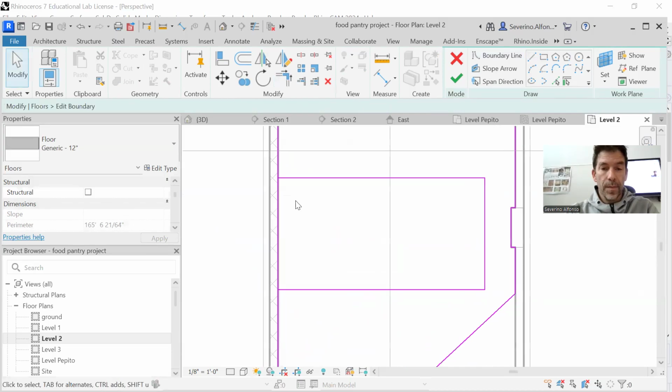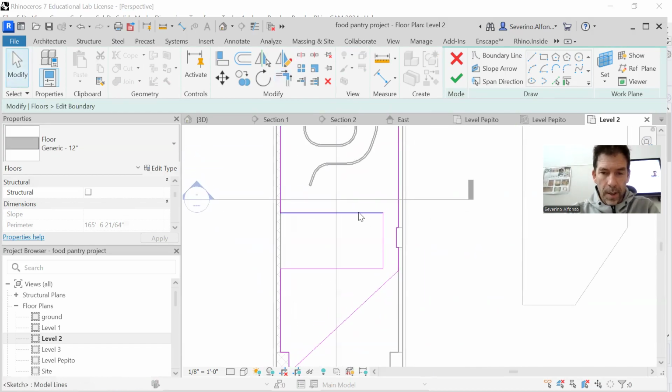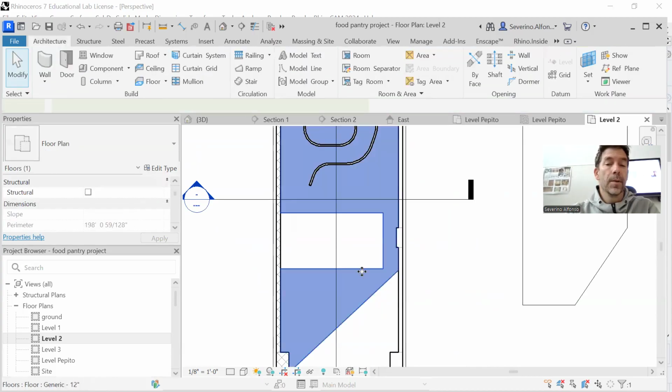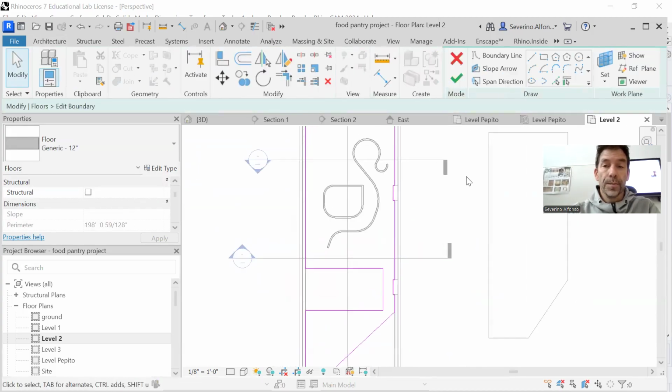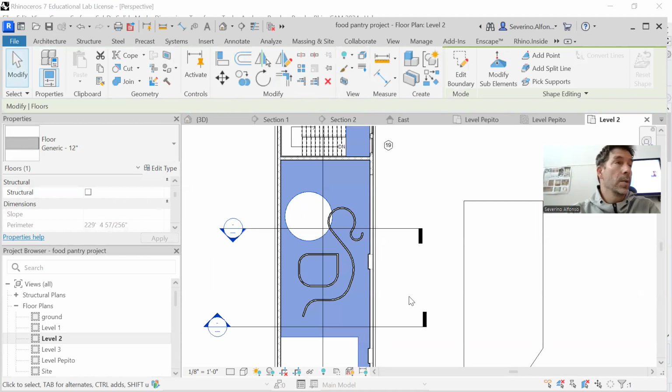And I can do what is called a split here in the middle and TR to create that situation where the polyline is coming in here and doing that shape, so then you have an opening in the middle. You can also do any shape in the interior of that polyline, whatever shape it is. If it's interior, we'll do a donut cut.